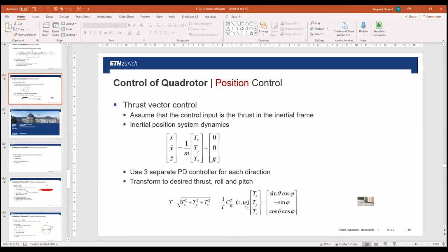Now, for the position, if you want to do a position control, you have the acceleration, you can double integrate, and then you would have the position, but you have an offset, which you cannot calculate. So for the position control, you actually need a position measurement. In free space, typically GPS gives you this information. Or in a system which is flying indoors, we typically have laser sensors or cameras on board, which give you in a given reference frame the position X, Y, and Z. And of course, you have to use this in the whole control. So control needs the input, and this is typically a measurement, and very often the measurement itself is a challenge.